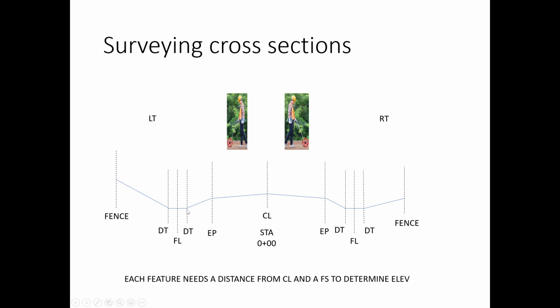And from the edge of pavement, normally there's a fairly smooth drop until you hit basically the side of the ditch, and kind of at the point where the ditch begins. So sometimes you can need, to establish the ditch if it's fairly wide, kind of each individual point there, or we could just kind of come down and say there's a flow line here. But a lot of times we want to see how wide the ditch is. So a right side of the ditch, a left side of the ditch, and then the central flow line elevation of the ditch, just to establish that.